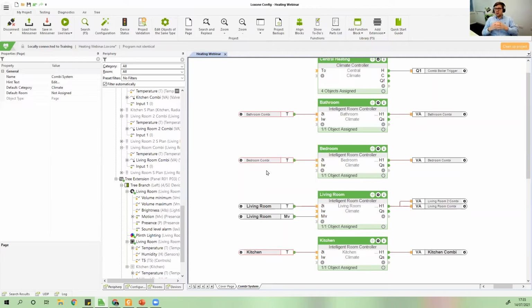If both switches are well placed, I would consider averaging. The recommendation we have generally been given by heating engineers is to not average temperatures, but to pick a single point in the room to read from. So it really depends on the layout and the principles of the room.